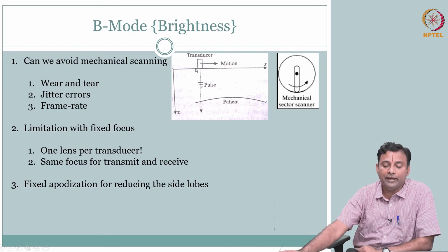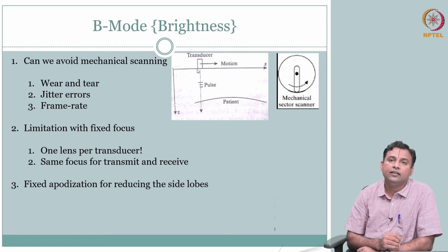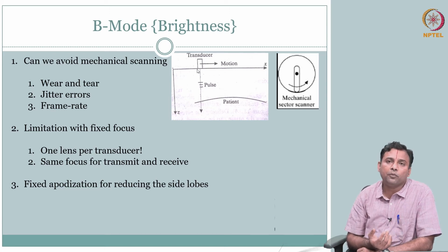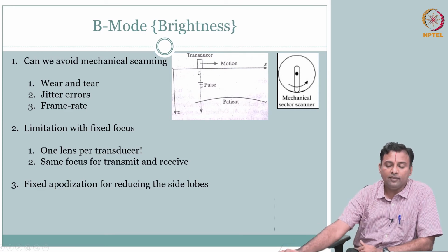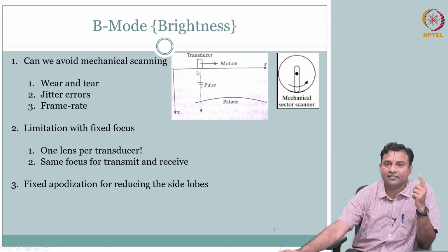So, you could have a material that does the apodization, but clearly you know from your signal processing, similar concept, you would have been familiar with filter design, main lobe to side lobe or ripple effect. You have a rectangle window or a Gaussian window, right. Same logic is in the spatial aspect here. So that means there are so many different windows that are possible, Hamming, Hanning, whereas if you end up doing one material which gives preference weight to the center, you can have only one profile, you can have only one window function, right.